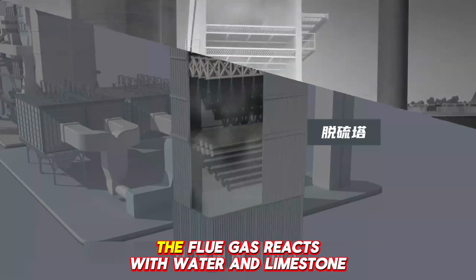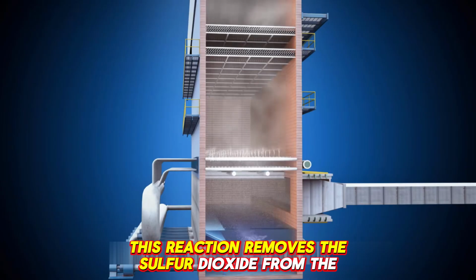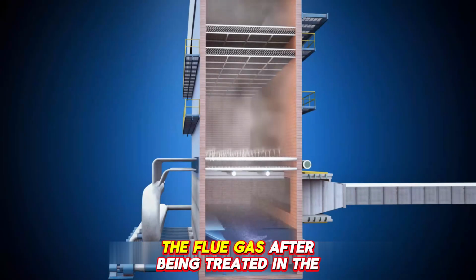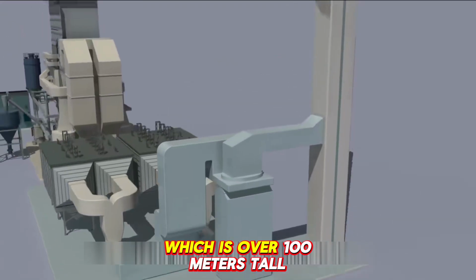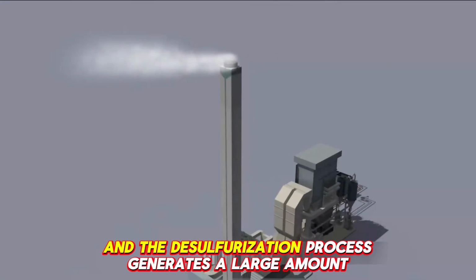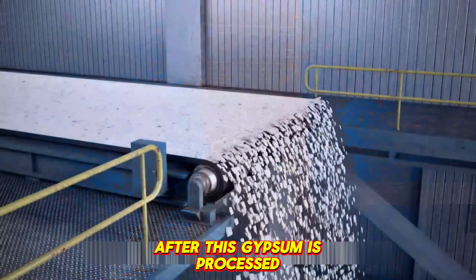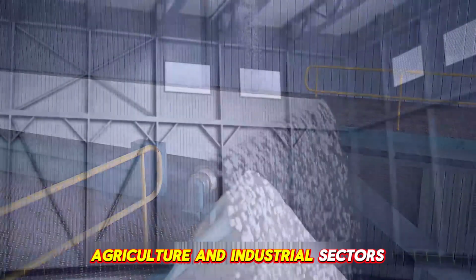In here, the flue gas reacts with water and limestone. This reaction removes the sulfur dioxide from the flue gas, thereby reducing air pollution. The flue gas, after being treated in the desulfurization tower, can then pass through this chimney, which is over 100 meters tall, and be released into the atmosphere. And the desulfurization process generates a large amount of gypsum. After this gypsum is processed, it can be used in building materials, agriculture, and industrial sectors.